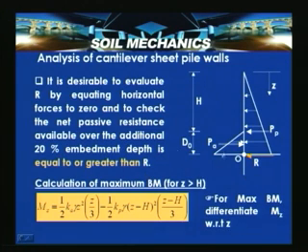So, here it is wrongly shown, this is PP and this is PA. Calculation of the maximum bending moment can be obtained for Z greater than H. That is, Z actually starts from 0 at this point and is then measured from this level downwards.